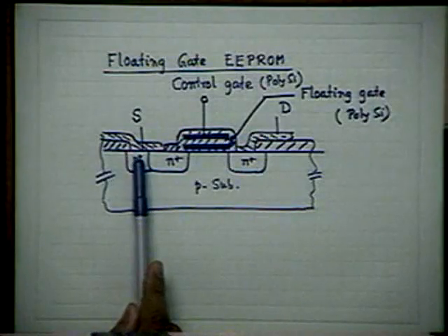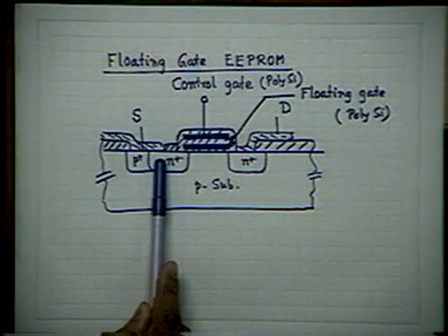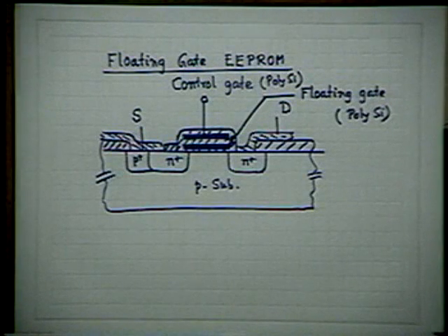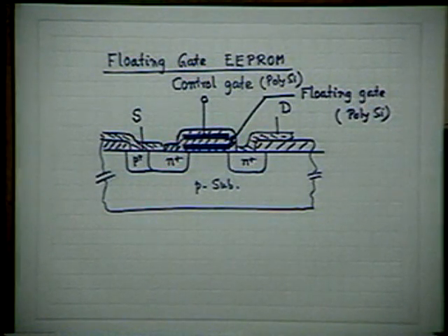You know, you have to take a contact from the substrate, all right? And if you keep a large distance between that contact and the N plus source, the probability of latch-up is more. One can show. Let us not go into the device details, but this is a very common terminology in MOS. This is called butted joint or butted contact.